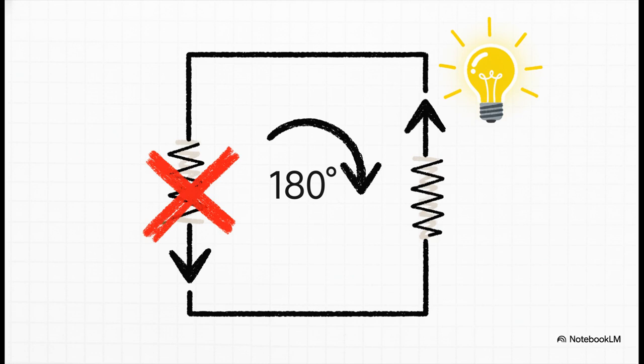In a real physical circuit, a basic resistor couldn't care less which way it's facing. But in a SPICE simulation, the math absolutely cares about direction. A negative current just means your resistor is placed in the wrong direction and needs a quick 180-degree flip. It's a prime example of how the software demands precision and builds much better engineering habits.